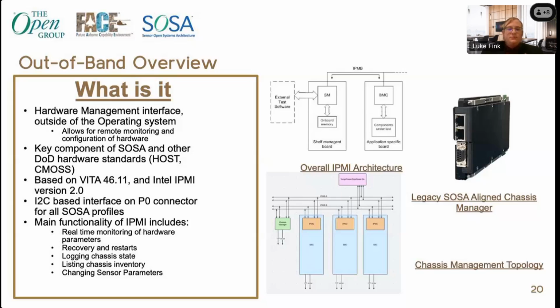state. So it's based in SOSA, it's based on VITA 46.11 standard, as well as the Intel IPMI standard, which is essentially a bit of an older standard that covers the same concept, but originally intended for server racks. So SOSA has adapted the system management that existed in older server racks for avionics chassis.